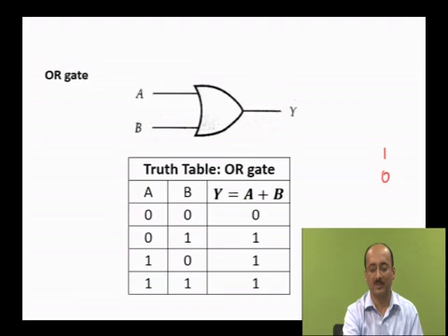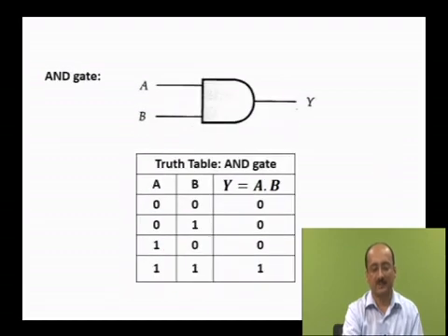It is not that 1 means 1 volt, 0 means 0 volt. So, this gate is such that its output will be high even if one of the inputs is high, as you can see here. If both inputs are high also, it will give high. Coming to the next gate, AND gate. This is a logic gate where only if both inputs are high, it will give a logic high. Otherwise, even if one of the inputs is low, it will give low output.